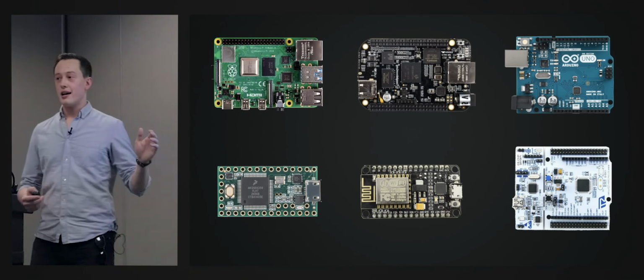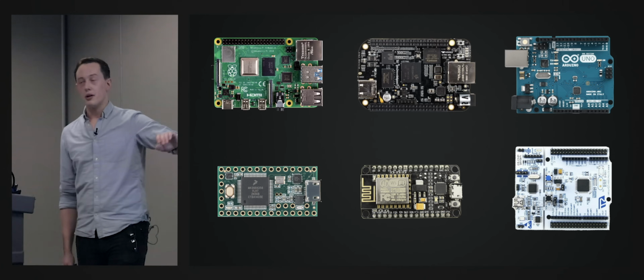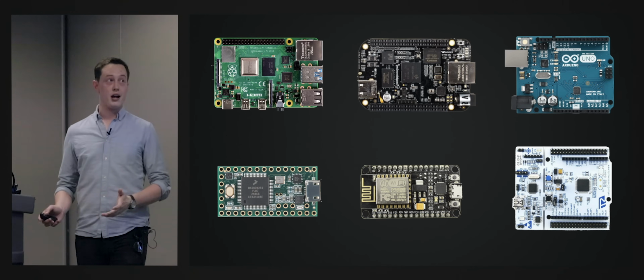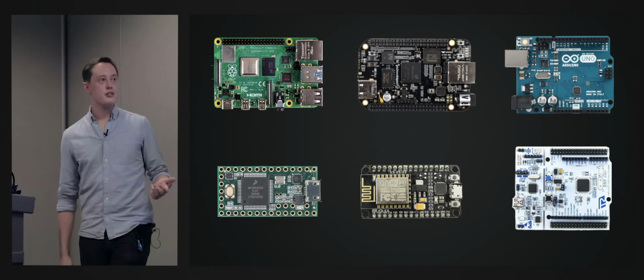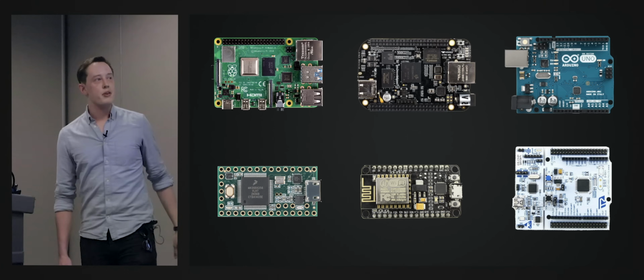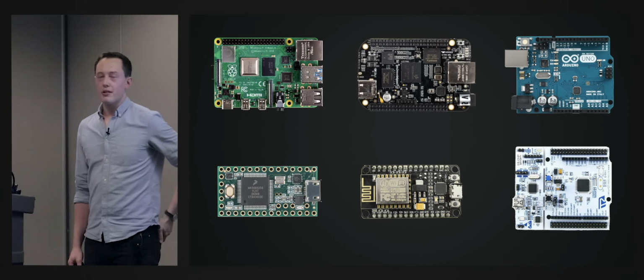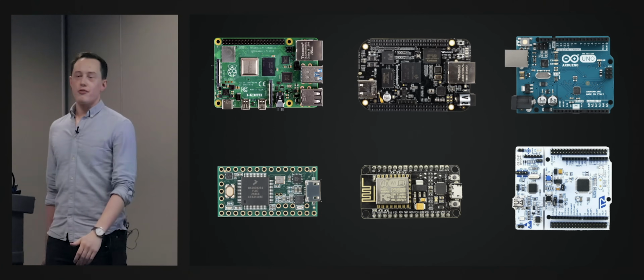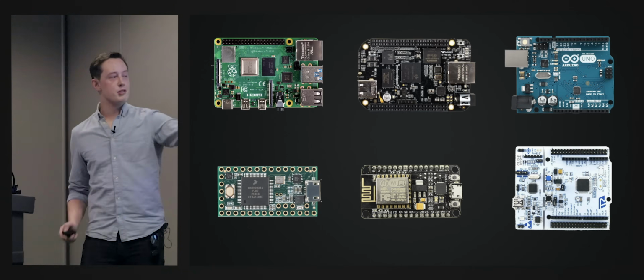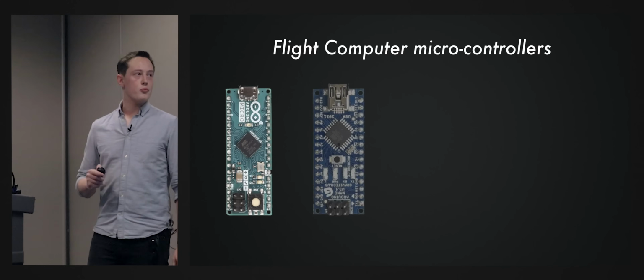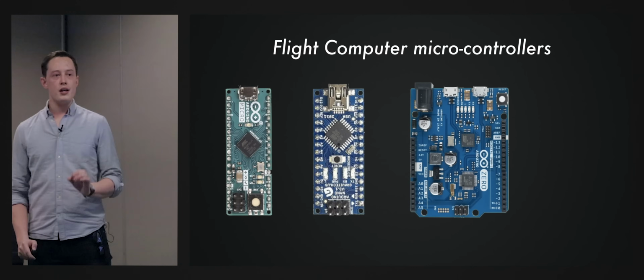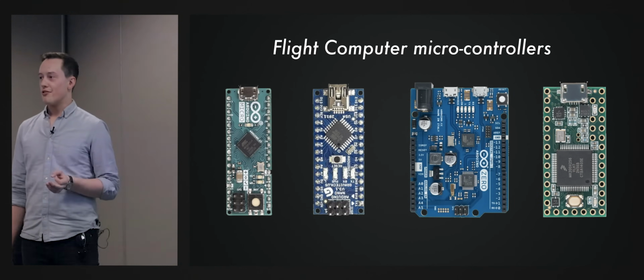The point is that you have many options when you're going through selection for what you want to drive your whole rocket. What's the primary MCU? I don't recommend going with the Raspberry Pi or the BeagleBone route. They're way overpowered for what you need, and honestly, the Teensy seems to be the best option. So just to reiterate here, if you wanted to pick from one of these 4 specific computers, these are all excellent options to choose from.